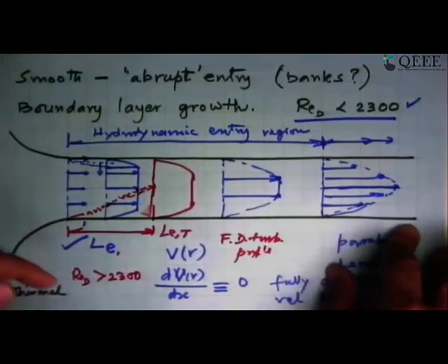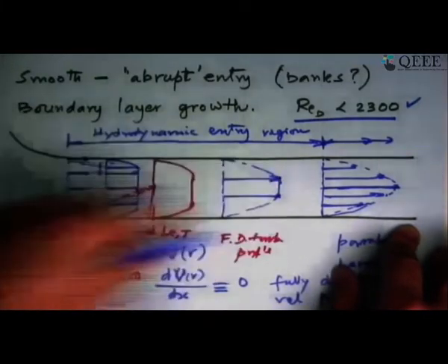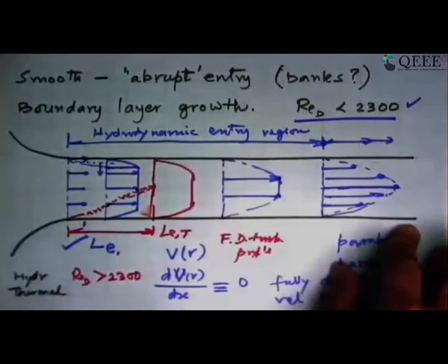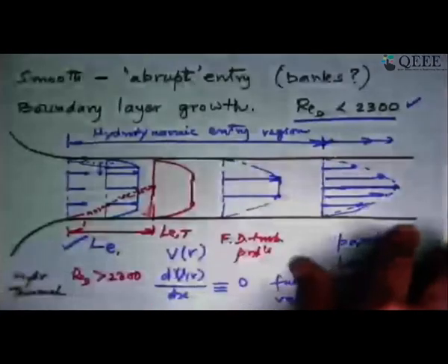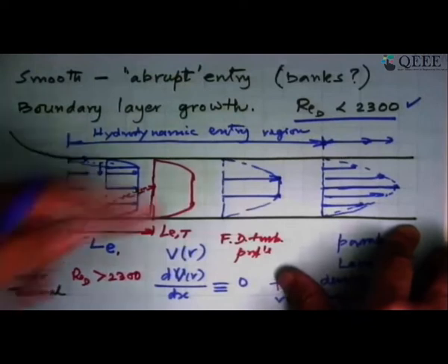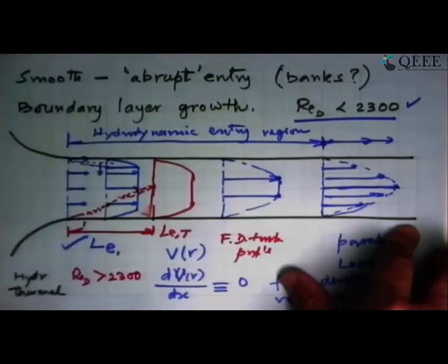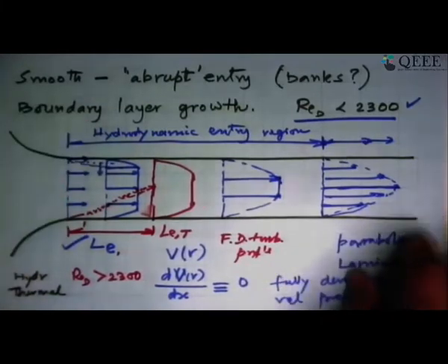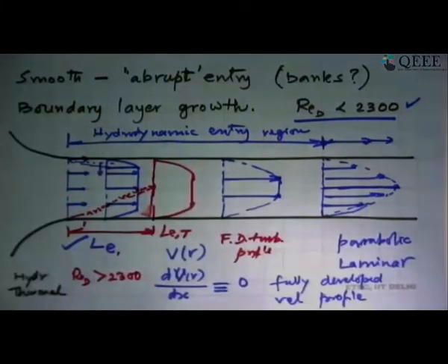The second is the case where, say, you have a tube going in and this is wrapped by an electric heater and you have a constant heat flux case. You'll also have a similar condition if this tube were getting solar radiation. Solar radiation also produces the same boundary condition of a constant heat flux at the wall. So you have two conditions that we need to look at, and that's what we will do now.